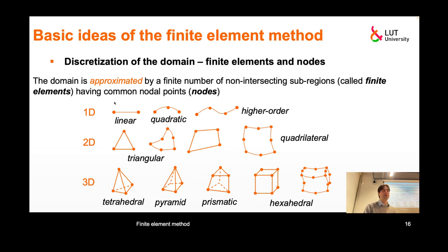In this case, I'm talking about the shape of finite elements. So one-dimensional finite elements, two-dimensional finite elements, and three-dimensional. Of course, in three-dimensional, there are a little bit more options on the basis of triangular and rectangular that you can build. It's not only hexahedral and tetrahedral elements, but also you can build some pyramids which have a quadrilateral shape in the base, and all other faces are triangular, or it might be a prismatic element.